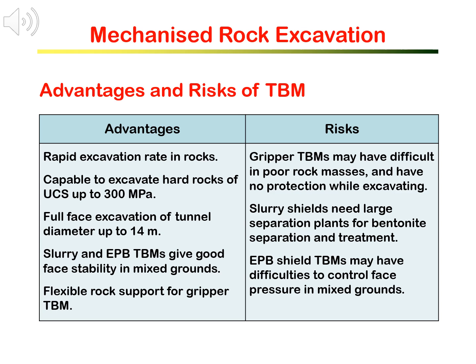Using TBM also faces risks and challenges. The key challenge is diverse geology and grounds, particularly mixed and challenging grounds. TBM is often selected or designed for a specific ground condition and is not ready to cope with changing grounds. Other risks for gripper TBMs, EPB, and slurry mixed shield TBMs are also summarized in the table here.